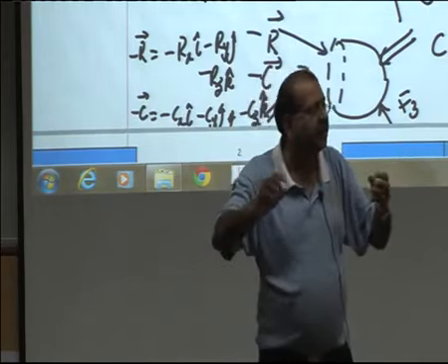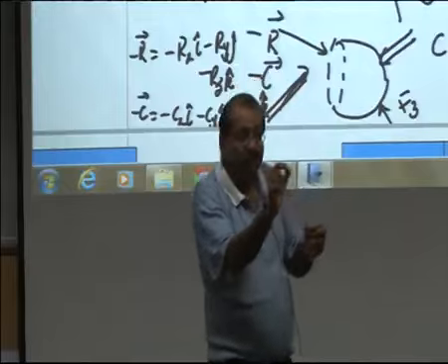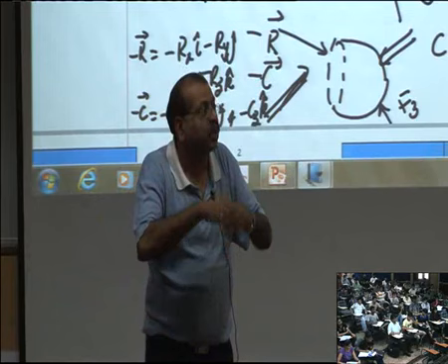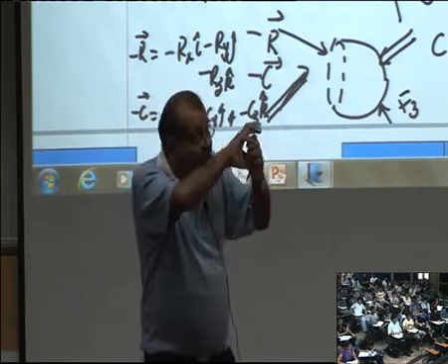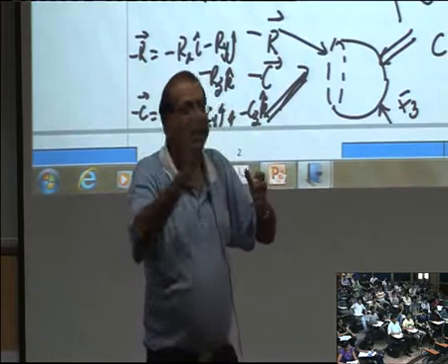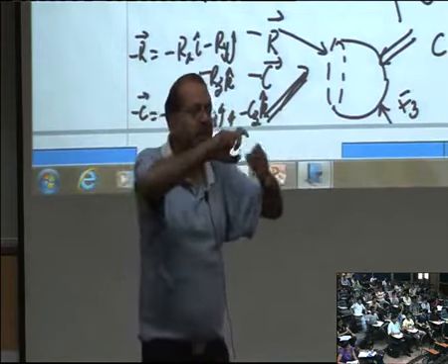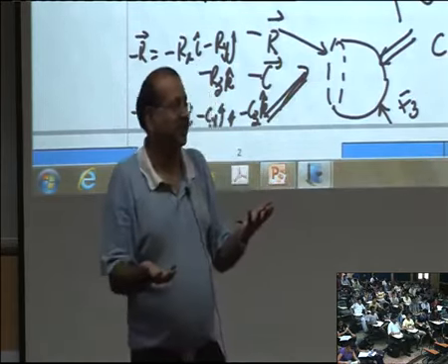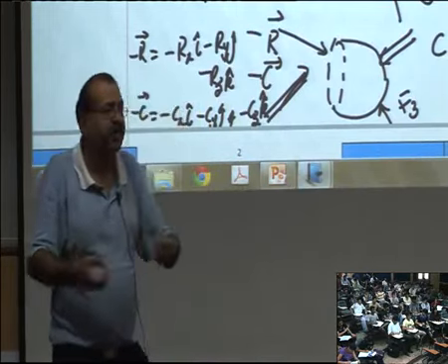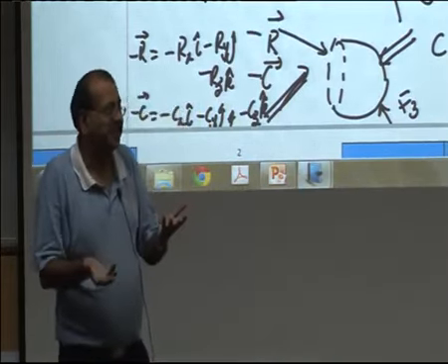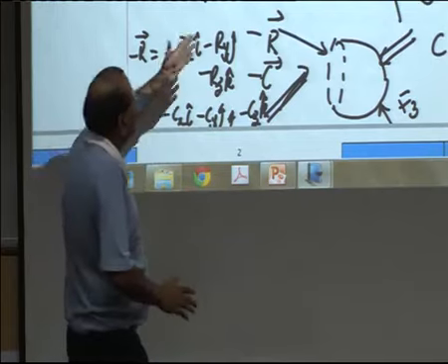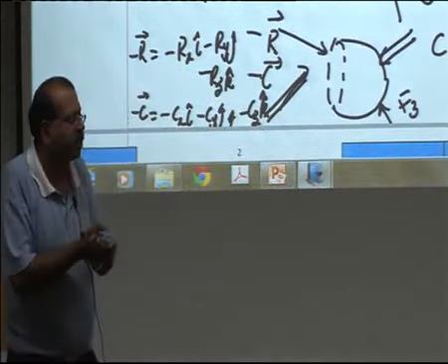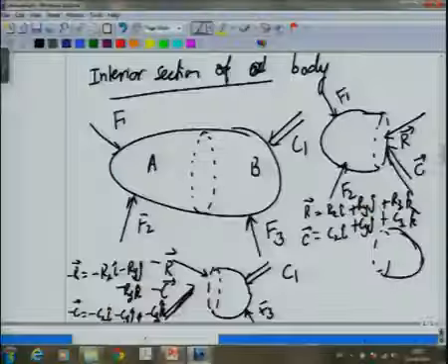Overall the balance may be right, but individually if at a particular part the forces and moments are not correct, then it may fail there. In terms of a better design, you would like to find what the minimum area should be for a given loading, so that the bar can take this load. Because extra area means more material, which means more cost. So, you want to prevent that cost. That is why these internal forces will be important, and we will see them in a couple of lectures when we talk of shear force and bending moment. We will talk of the internal forces.